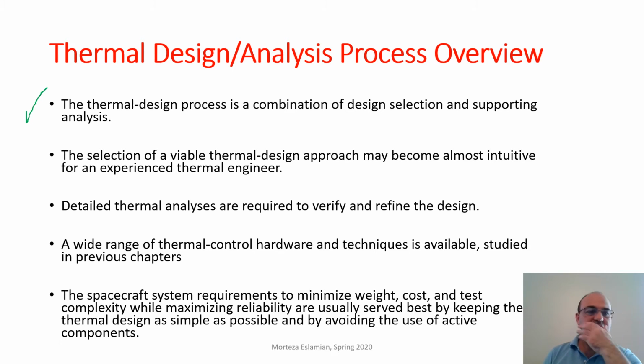Let's say for a standard satellite, most experienced thermal engineers know that they would choose multi-layer insulation, what kind of optical coating to use for the radiators, and also heat pipes. So it could be as simple as that.